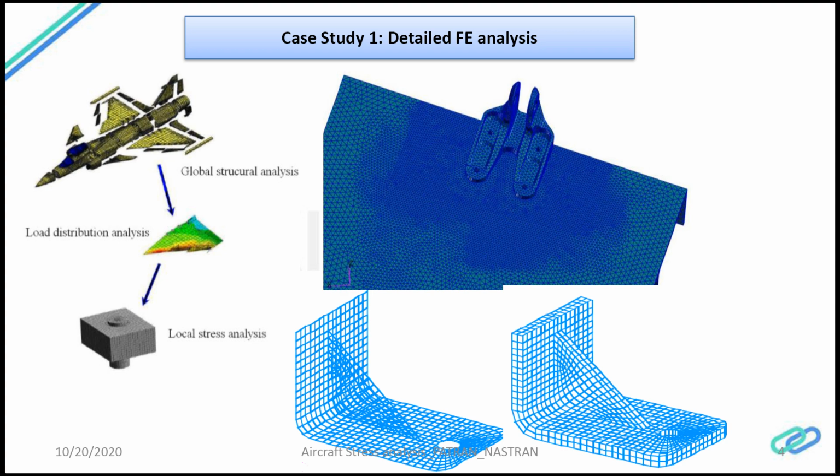For core we take core shear stress, for skin panel we take the maximum in-plane stresses. So those kinds of questions.